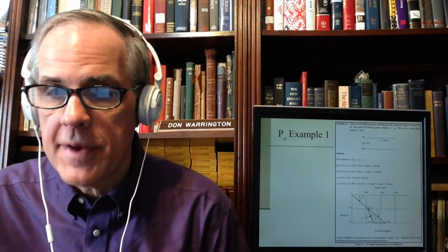At 20 feet, the total stress is equal to the total stress at 10 feet plus another 10 feet for that layer times 110 PCF. Now you say, well, why can't you do 20 times 110?